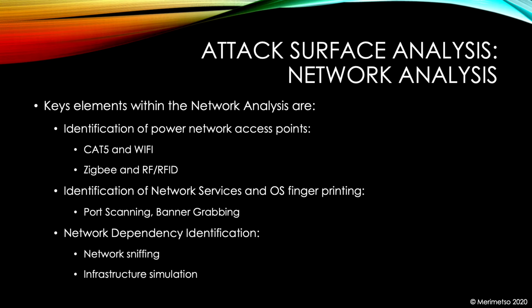Many embedded systems today make use of web servers and web engines as a way of doing simple configuration. They also make use of SNMP, Simple Network Management Protocol, as a way of allowing you, the user, to configure the device. And we can also do network sniffing and infrastructure simulation. So network sniffing is sniffing the infrastructure, the ether if you will, that the device is communicating over. And if it's communicating to servers, perhaps simulating that server and that infrastructure to see if there's a way we can inject data into the device.